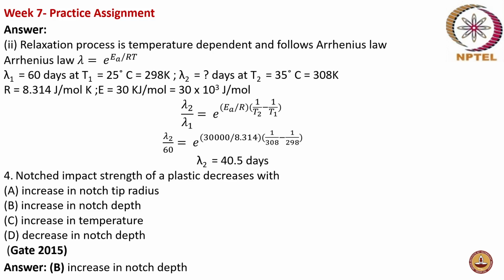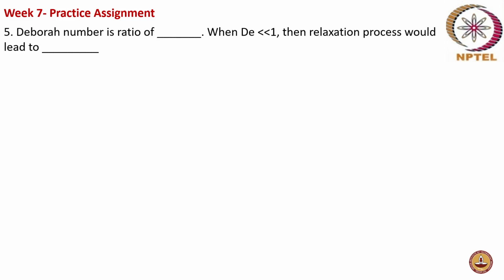You remember the Izod test and Charpy test, that notch diagram, a V-shaped notch. So when you increase that notch, your impact strength is lower, it easily breaks. The energy required to break it is lesser. That is what this question says. Next.